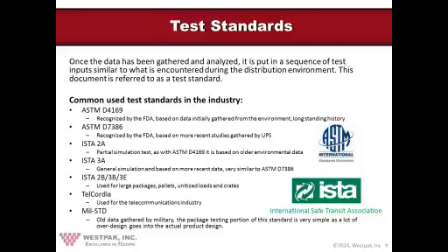A newer standard is ASTM D7386, which is based on more recent data, dating back maybe 10 years, a little more or so, gathered with the help of EPS. This standard includes more recent data, profiles, drop heights, and so forth, and seems to serve its purpose well also. Both these ASTM standards are recognized by FDA, because ASTM is a consensus body. If you're a medical or life sciences company, it's recommended that you use one of these standards so you're not questioned by the FDA in case of an audit.